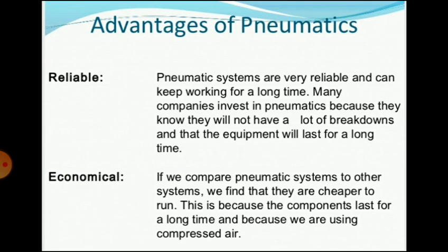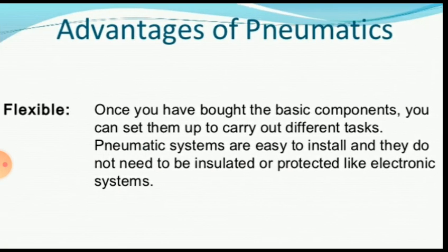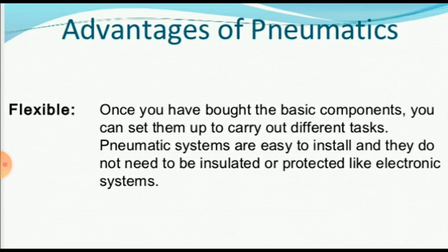Then reliable. Pneumatic systems are very reliable and can work for a long time. Then economical. If we compare pneumatic systems to other systems, we find that they are cheaper to run. This is because the components last for a long time and because we are using compressed air. Then flexible. Once you have bought the basic components, you can set them up to carry out different tasks. Pneumatic systems are easy to install and they do not need to be insulated and protected like electronic systems.